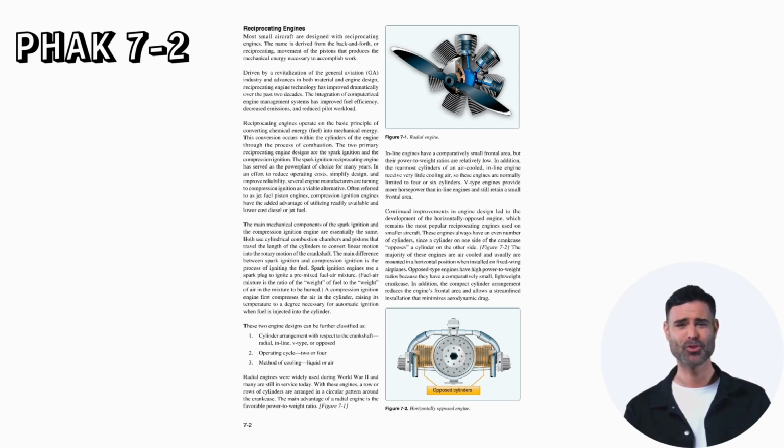In an effort to reduce operating costs, simplify design, and improve reliability, several engine manufacturers are turning to compression ignition as a viable alternative. Often referred to as jet fuel piston engines, compression ignition engines have the added advantage of utilizing readily available and lower-cost diesel or jet fuel. The main mechanical components of the spark ignition and the compression ignition engine are essentially the same.